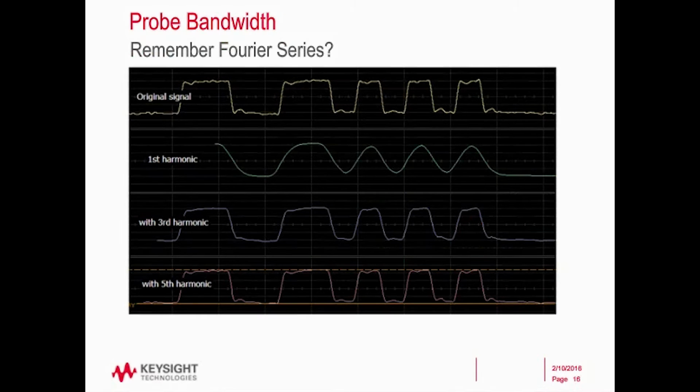Now, let's say you're saying to yourself, well, that's great, Kenny, but I don't know the rise time of my signal. What I know is something like clock frequency, right? I know the frequency of the clock that's running my digital system. Well, okay, I'll tell you how to answer that, but hold on. First things first. We have to go back a little bit and remember your Fourier series. Fourier series says I can build any waveform I want out of a series of sine waves.